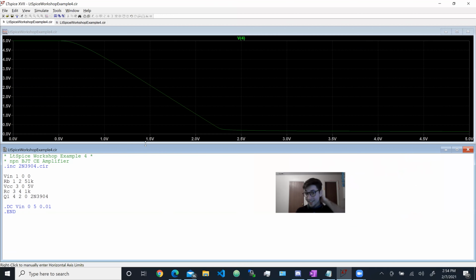Yeah. Okay, so that is actually true. What's going on is our input, we are sweeping it. So we start from 0. 0 volts is our input, and our output is going to be high. And then we have a transition. And then if we give higher voltages for our input, then our output's 0. What does that remind you of? That is a NOT gate. If our input is low, because it's from the 0-ish area, our output's high. But if our input is high, then our output is low.